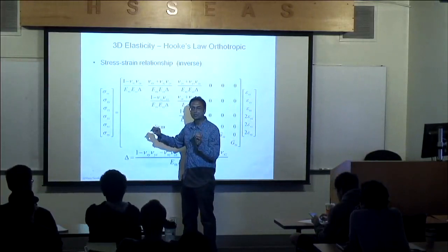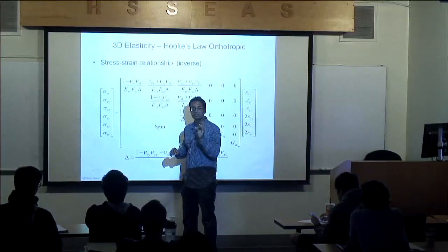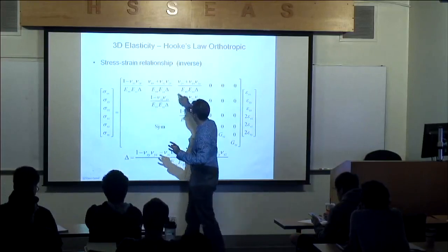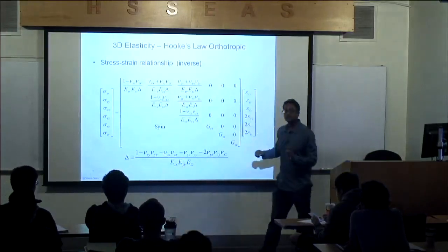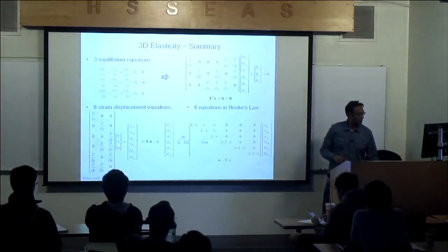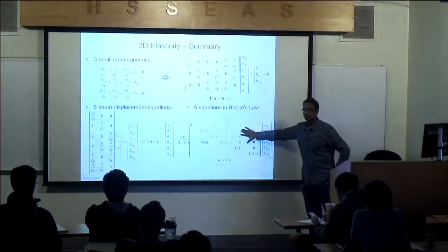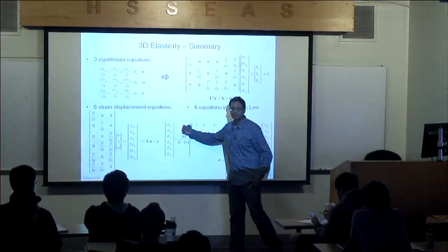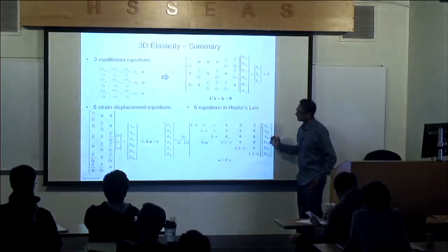And then in Abaqus, under materials, you will use engineering constants. And then you can define the 9 different constants for the composite. And that can be done very, very quickly. So this matrix can be defined either for isotropic or composites, no problem. And you can see here it is a 6 by 6. It relates stress to strain.